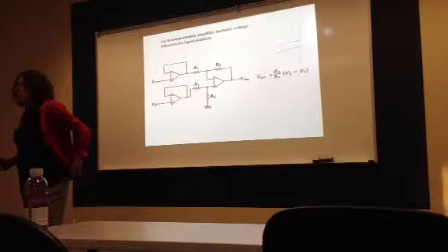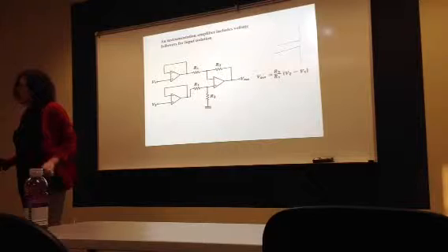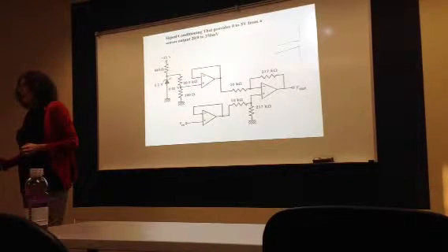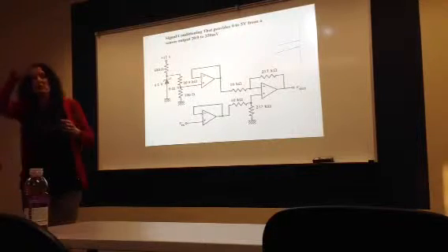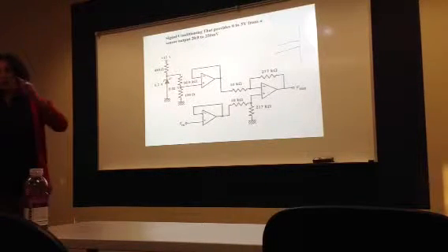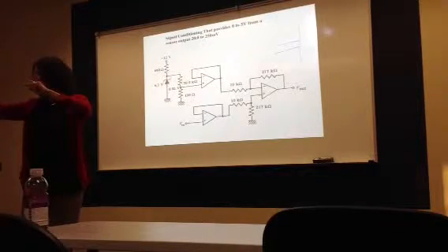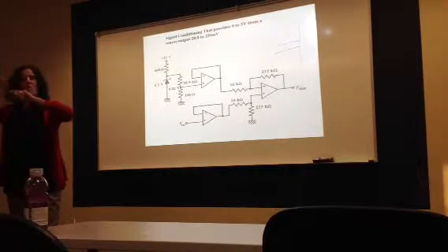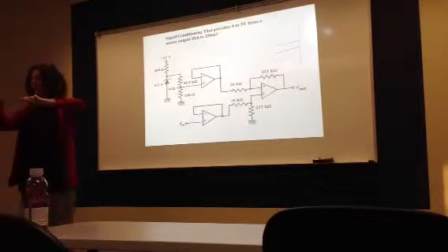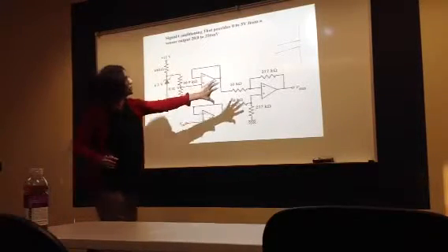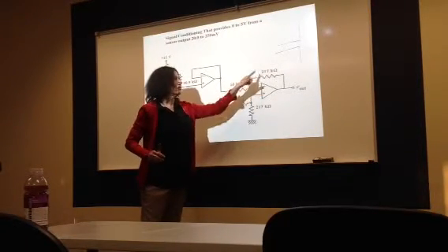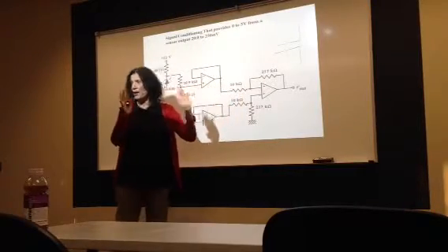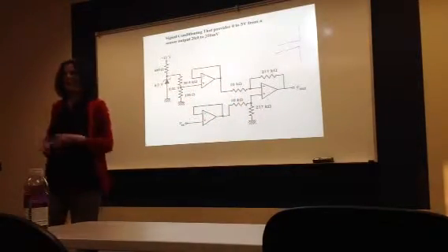The instrumentation amplifier includes voltage followers for input isolation. We did that also before. Signal conditioning that provides 0 to 5 volts from a sensor output of 20 to 250 millivolts. If you remember, the output was going from 0.02 volt to 0.25 volts, and the output from 0 to 5, and we got y equals mx plus b, and then we had to take a common factor. Finally, we put this equation, and the gain here is 217, which is about 200. You remember this problem? Yeah, expect to do all of that in the final.